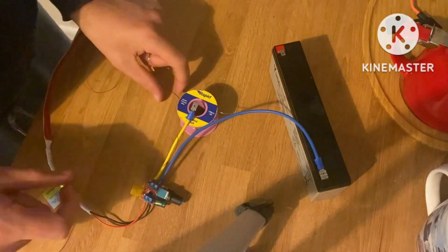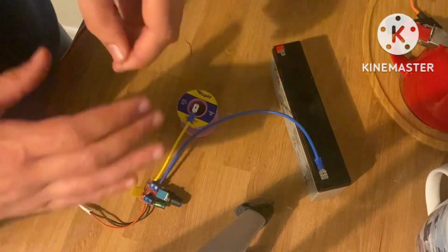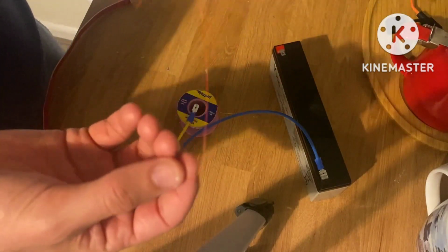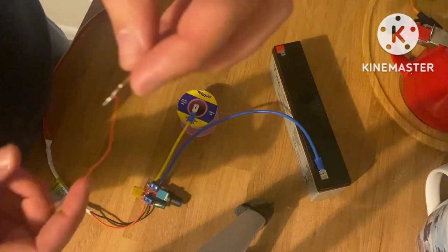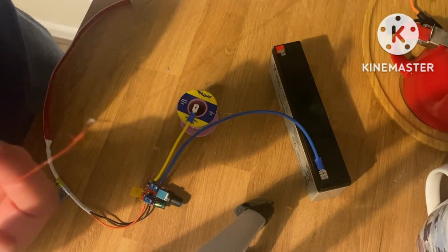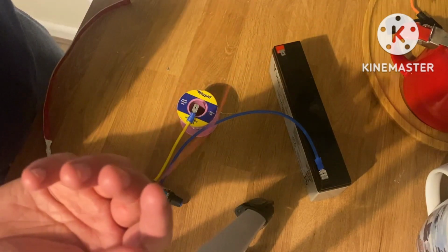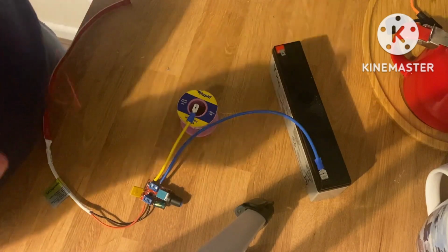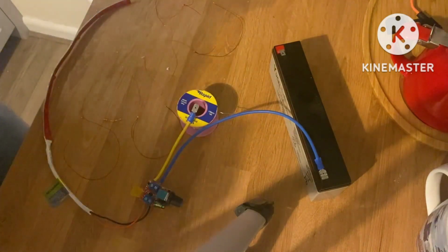Now, this is all I've done for every single one of the deck lighting LEDs on my model. Yes, the wires get trimmed, yes, they get put into smaller spaces, but this is the exact same principle. Every single one of the deck lights starts with a resistor, then it's just a long chain of 4 LEDs which then goes back to 0 volts. That is the same process, and it's just copy paste, copy paste, copy paste. This is all that the lighting circuit boils down to.